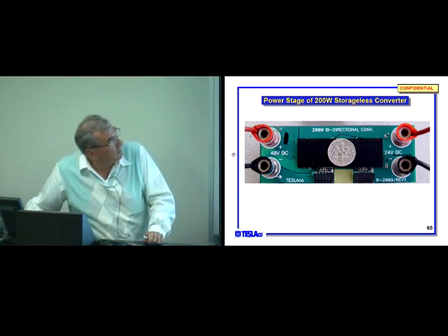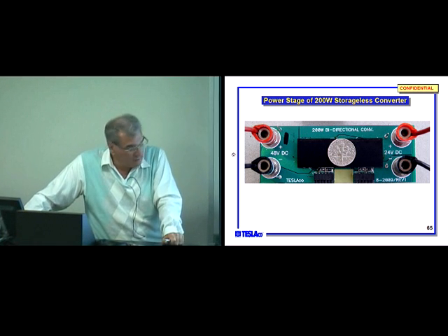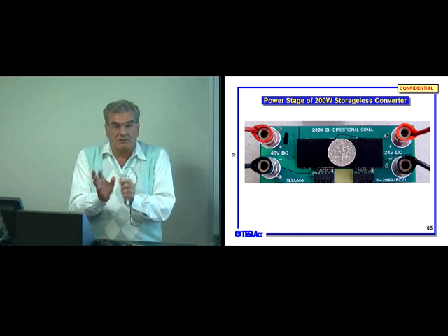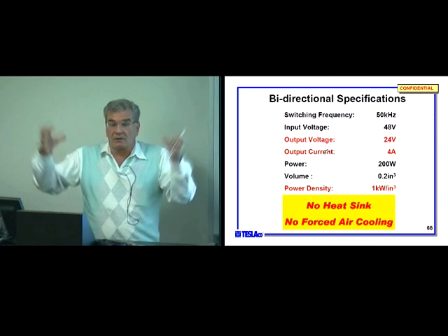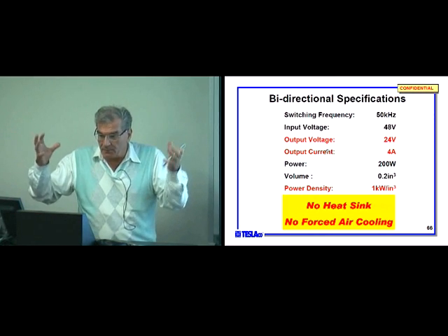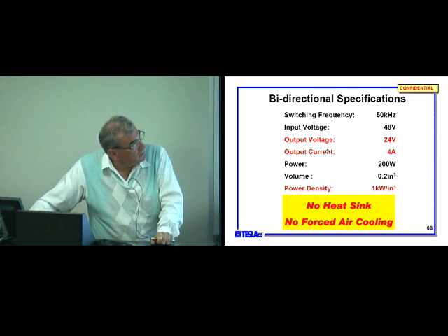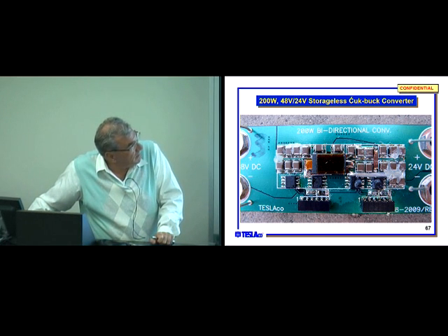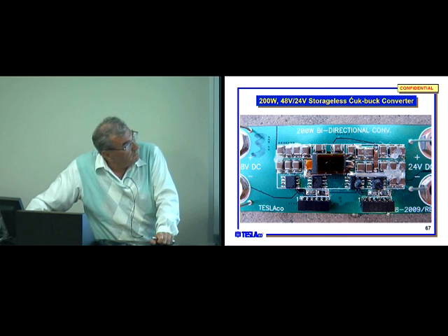And now another point I want to show you, and it's down in the illustration. What can we do? This is AC to DC. Three stages can be done in a single stage with high efficiency. What can we do with DC to DC? Normally, DC to DC converters have a big storage inductor, and big size, and efficiency goes down. Well, I'll show you here. This is a 200-watt converter, which has very small size magnetics, and it doesn't operate at megahertz to get small size. It operates at 50 kilohertz for 48 volt to 24 volt output, no heat sink needed.